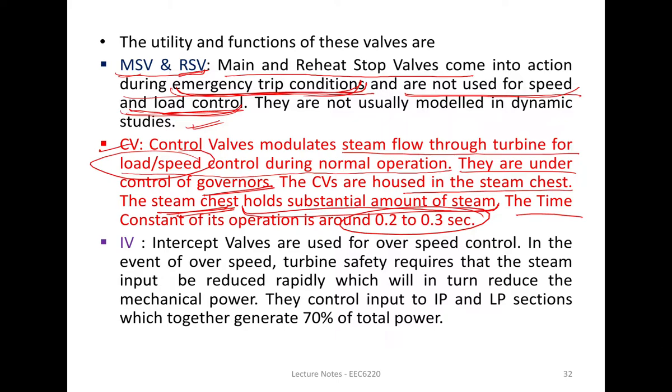तो इससे हम कंट्रोल करते हैं स्पीड भी और लोड भी, whatever the amount of steam we are going to give at the input through the control valve, that much output we are going to get, and it's simply steam and load both depend upon the same thing, because how much the speed of the turbine is going to increase, in the same proportion you are going to get the output from the generator, all right.